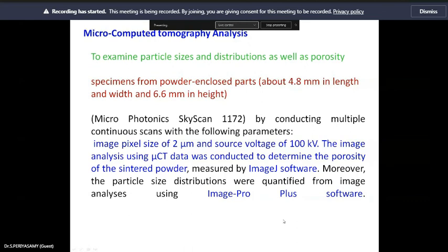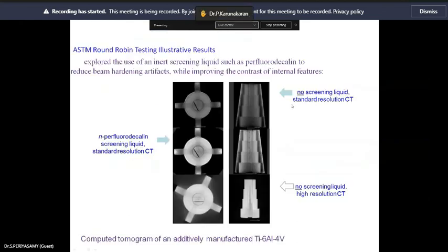Here you have cracks because of the high temperature difference in the gradient between the melt pool and the surrounding. It may lead to cracks that initiate due to this thermal stress and ruptures. The compositional segregation in some alloys may intensify the cracking.